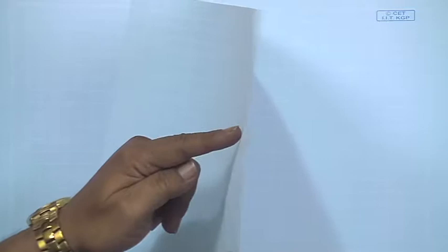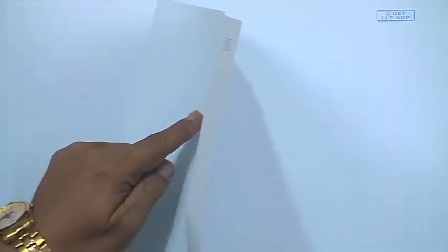So, say 60% to 80% you want to concentrate, or 60% to 90% you want to concentrate in a film. So, what you will do, you will fall this one side, say if we take this as heat exchanger. So, one side you will make this like this, one side is the film which is falling and another side is your heating medium. So, while this fluid is falling from here to here, by the time it falls from there to there, it will get concentrated, right.